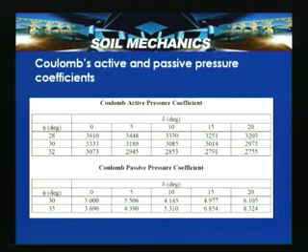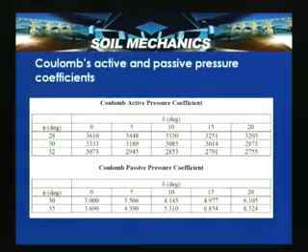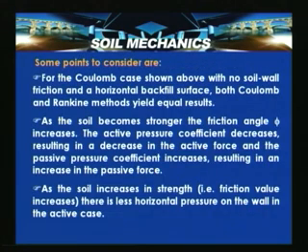In this case, for different wall friction angles and friction angles of the soil, we have given Coulomb's active pressure coefficients and Coulomb's passive pressure coefficients. For a special case like we discussed, with delta equal to 0 and friction angle equal to 33, the Coulomb's active coefficient will be equivalent to the Rankine active coefficient. So, Coulomb's solution converges into Rankine's solution if Rankine's wall conditions are satisfied. Let us look into the deliberations based on this exercise.